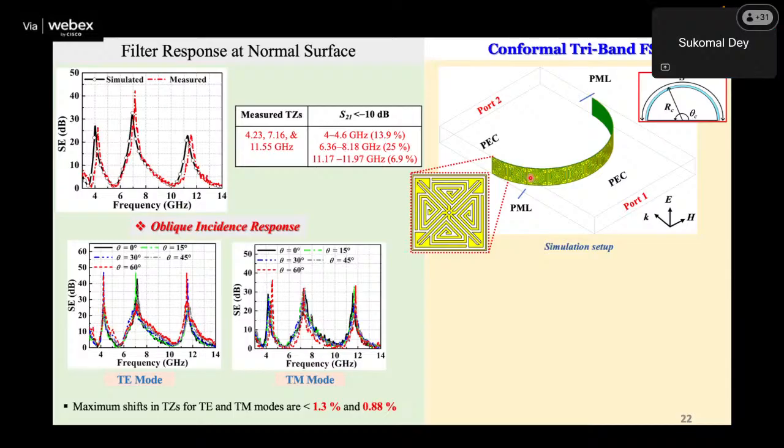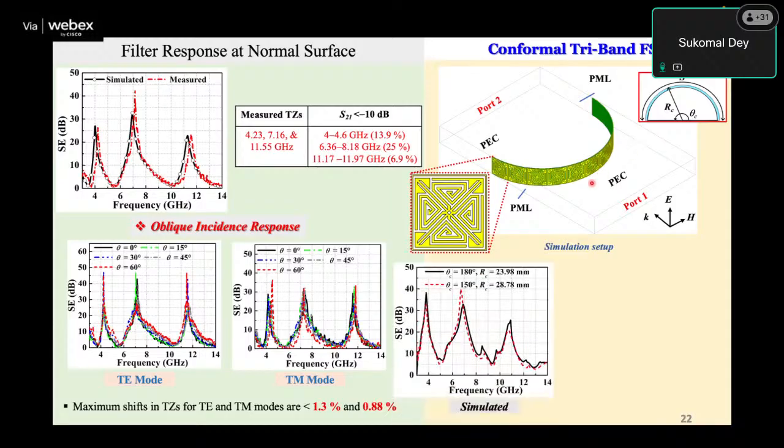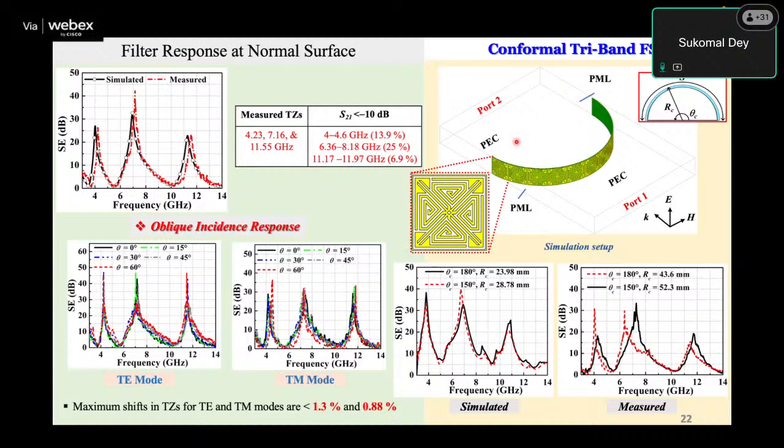in radome applications, right? Inside the radome you have the antenna, correct? So in most cases your structure has to be, to some extent, transmissive at some frequency and reflective at some other frequency. So this is the response when you make the structure conformal. This is the response with respect to the shielding effectiveness.